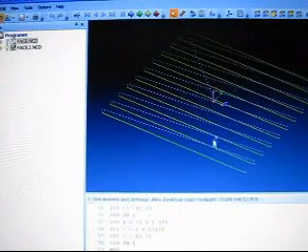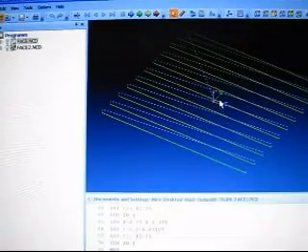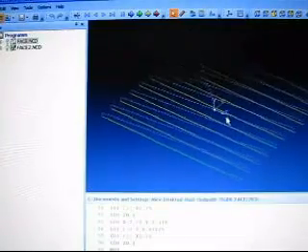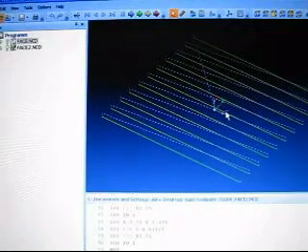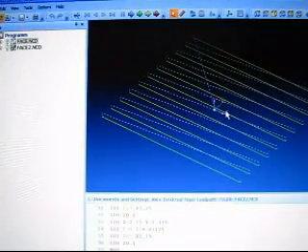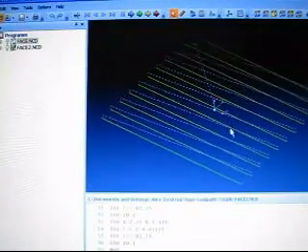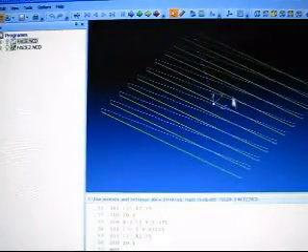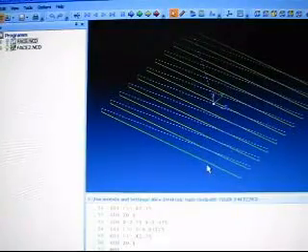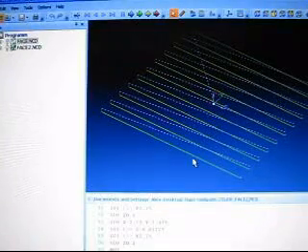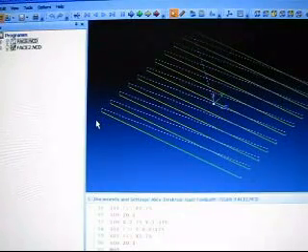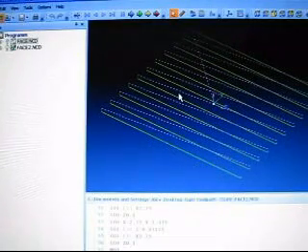And when you do that, you've got to flip that inside outside thing around the other way. It has a little button on there for conventional and mixed and climb that has no bearing on this because it's an open chain. It's just a single entity. Keep in mind you can reverse these things, and you've got to know the orientation of them, so the way in which you draw them matters to the way the toolpath is going to project. So in this case, let's say that I drew the line from left to right and did all the parameters the same.